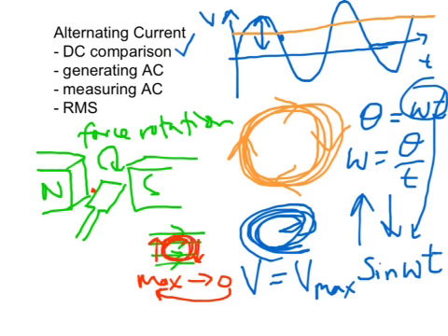It's only when it's cutting the field perfectly that you get a maximum, and you get 0 when it's going parallel with the field in the direction of movement, and somewhere in between it'll be a function of this sine thing. But we want to get them all pointing upwards. That's roughly how a DC generator would work. Most people don't use DC generators, but it's important to look at this to understand the concepts.